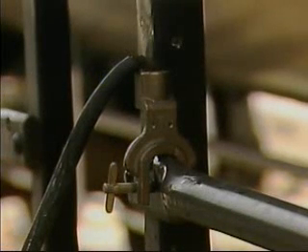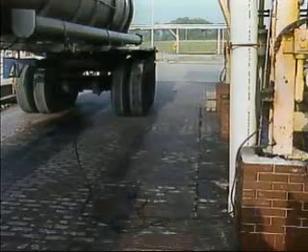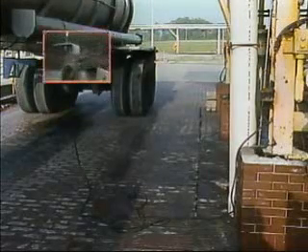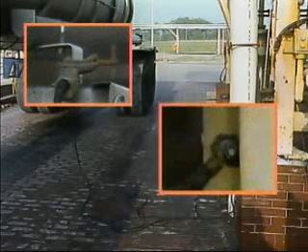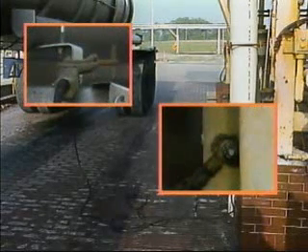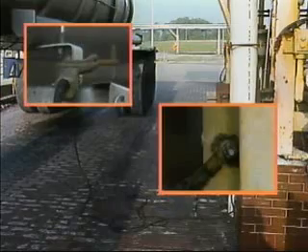The cable should be securely attached before the manway cover is opened, and it should remain in place until the cover is closed. When a grounding cable is properly attached, one end is connected to the metal frame of the tank, and the other end is connected to a grounded metal structure or piping that's separate from the tank.